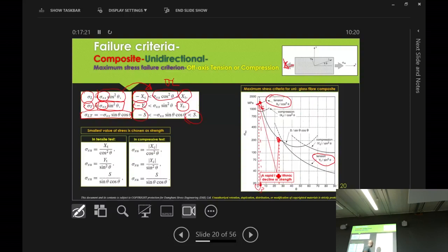And as you go along, let's say you get to 90 degrees, the strength goes around between 20 to 40. Let's say 35 at that point. So you can see, as the orientation theta changes, when you're at 0, you get the best in terms of load bearing. The orientation changes, let's say to 30. It goes more towards shearing.